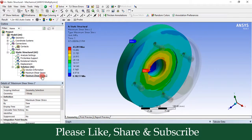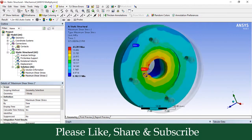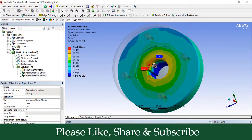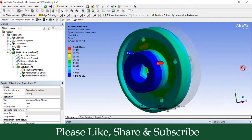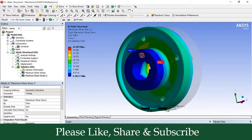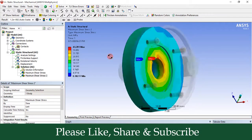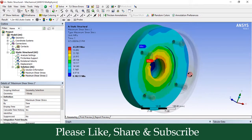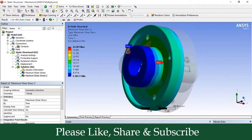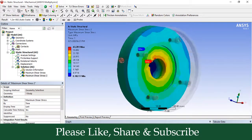So now this is the maximum shear stress for only input flange, where you can see here at this point there is a maximum value of shear stress, and here there is a minimum value of maximum shear stress. So shear stress is maximum at this point of this input flange, and it is minimum on this point of hub for the input flange.